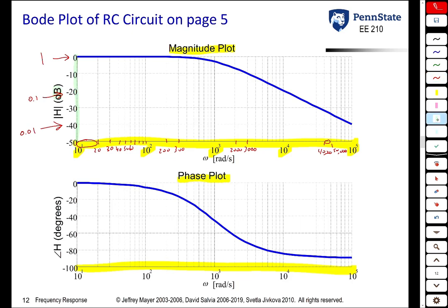For the phase plot, the y-axis is just your traditional angle in degrees, so there's nothing special there. But in the magnitude plot, you do need to remember that your y-axis is in dBs, so you interpret those numbers differently than you would in a standard frequency plot. Finally, mentioning again, a negative dB does not mean a negative number in the sense that we're used to. What it means is a gain less than 1.